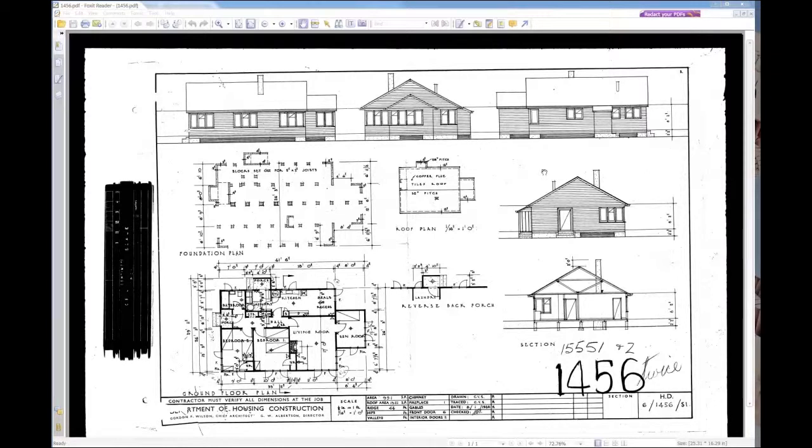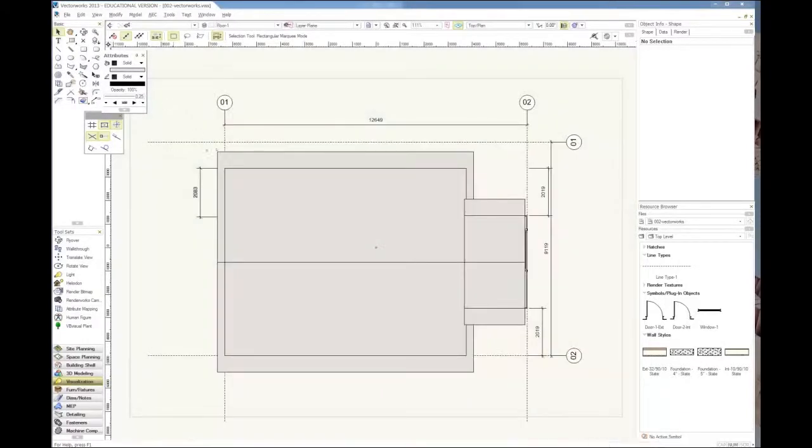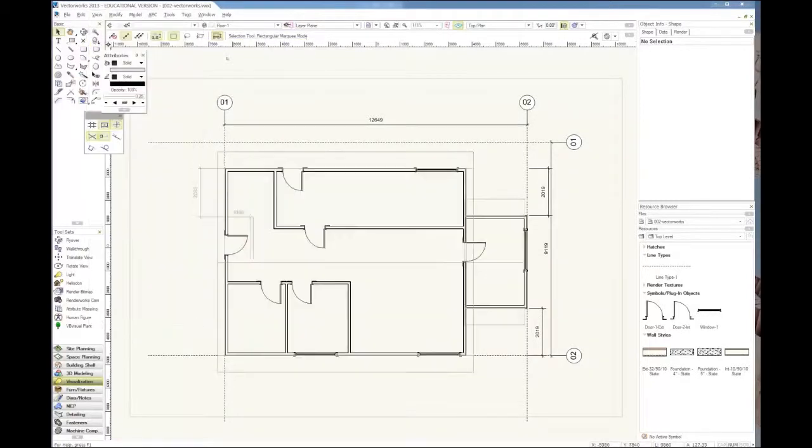And if we set up a sheet layer in Vectorworks, then we can put all these different drawings all on the same sheet, with dimensions and whatever as well on them. So how we do that is, first of all, I'll just put a plan on. So I'll go 0 for the plan, and I'll put it back on. If I go to standard view, layer options, and then grey, snap others. So I'll put something like this plan on.